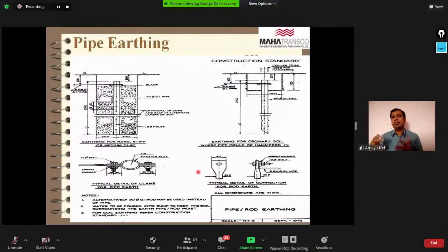Coming to pipe type earthing, as we are currently working in the EHV field, in MSTCL we have a 3-meter galvanized iron pipe. In the bookish style we use a perforated pipe, but in practical work we do not use the perforated pipe. We use only a 3-meter GI, that is galvanized iron pipe, for pipe earthing. We dig 3 meters and make charcoal layers. Depending on that, pipe earthing is ready. I'm covering this very briefly, because we know all these things.